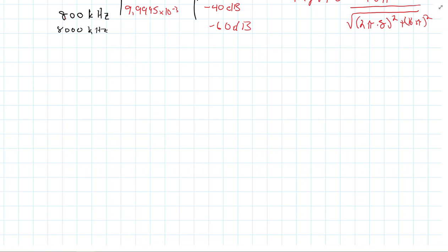Okay, so let's briefly review where we're at here with filters. Remember, we're currently looking at passive filters, which only involve resistors, capacitors, and inductors. We won't really be able to get gain out of passive filters. Active filters, which is what we'll talk about once we finish with passive filters, will let us get gain. So not only will we be able to filter a signal, but we'll be able to amplify it at the same time.